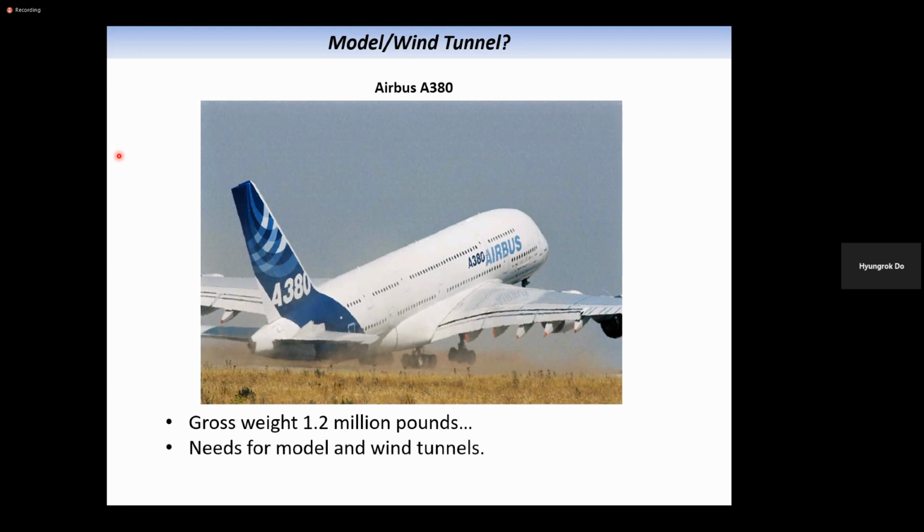Then you can do measurement better, and you can get much more useful information from the wind tunnel testing compared to the in-flight measurement. In-flight measurement is very limited. Let's say this aircraft is flying at high altitude, and it should have some pitot tubes and pressure sensors and temperature sensors outside probably, and those sensors are recording the flow conditions around it. But you don't have many sensors around it, and the sensors are providing information, but it is quite limited.